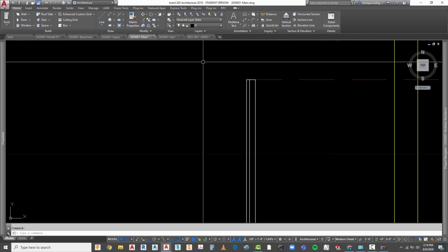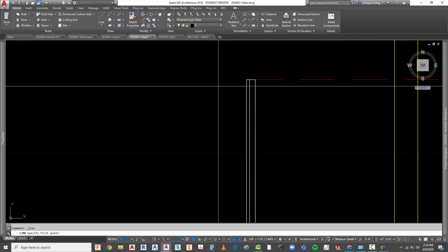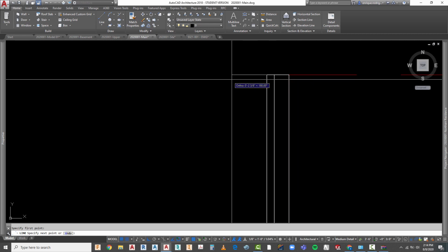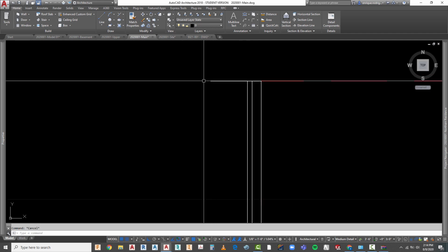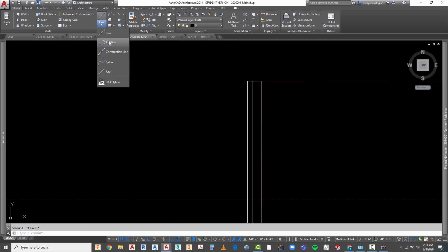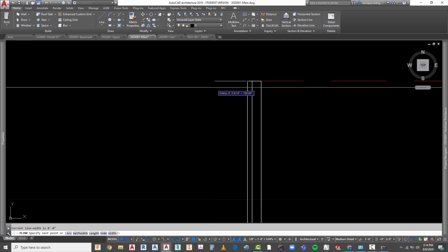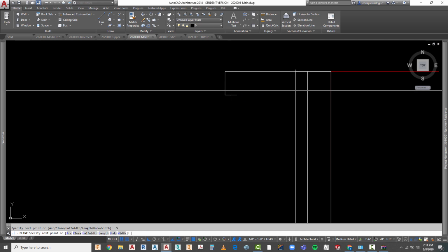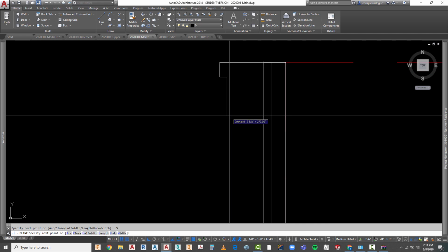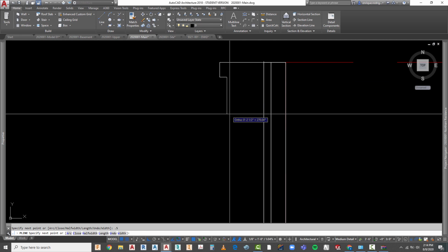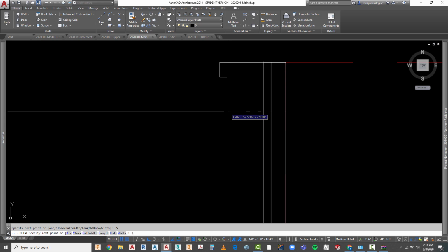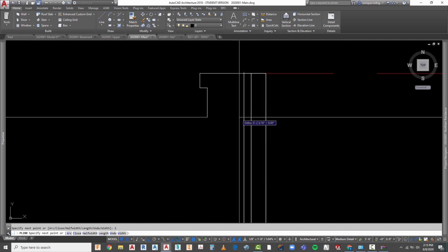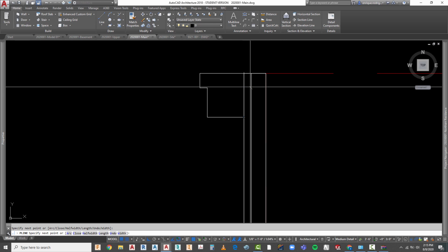And we're going to do pretty much the same thing that we did before. I'm going to create a polyline. And I know I'm going to be rotating it, but this is a good start for me to do it. I'm going to come out 4 inches. Actually, let's just come out 3 inches. Let's just come out 1 inch down. Let's come out 0.5 in this direction. What I'm going to do is come down about another 2 inches down. I'm going to come across, and finish up right there and close up.